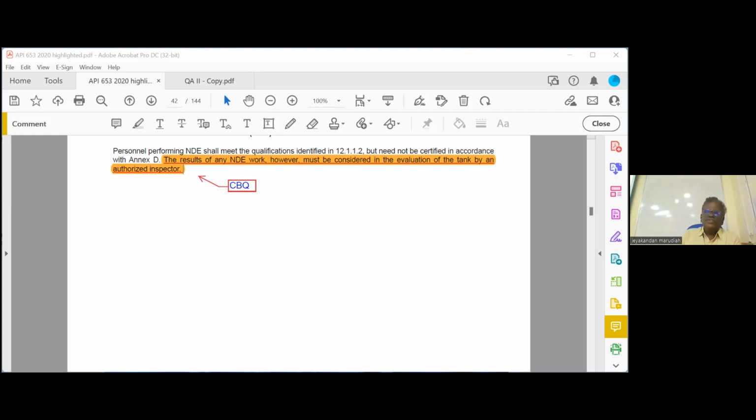But when it is severely leaking, we get the evidence only from the foundation. Yes, from the foundation you can find out. That's why we use channelizing outside. Any leak will come outside. They will monitor how much it is leaking. They know the level in the tank and how much it is reducing. If it is severely leaking, then we have to empty the tank and go for repair work.